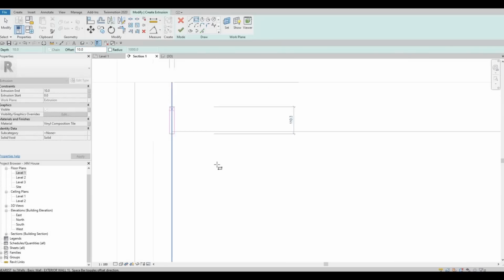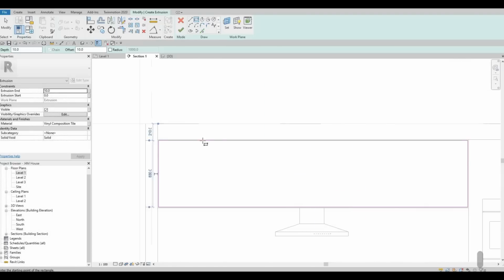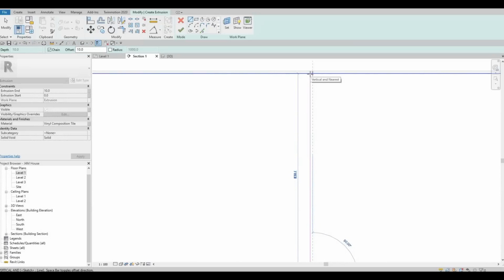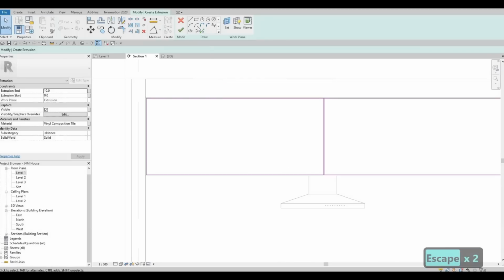Once you select that, we could use rectangle and then offset this one to 10. Here we offset it to 10, but we want it from the inside, so just click on spacebar and then select that on the corner. After a while, I want to add the cabinets right here in the middle, so this is a perfect spot. And then another one right about here, but let's remove the offset right here. We could use this and then offset that. So that's much better.